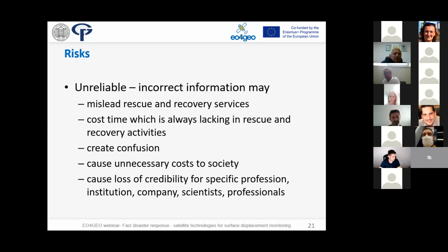So basically, if there was some sinking of the surface, at least what should be done is that the height of the river dams should be checked and controlled, because if at some location the surface has sunk, it could be a reason for some additional works to ensure protection from flooding, for example.